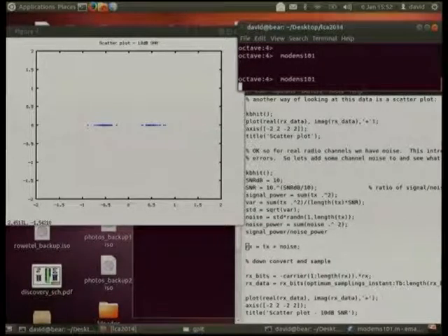Now this is a signal to noise ratio of 10 dB, which is roundabout the limits of analog communication if you're transmitting single sideband or voice. But you can still see, for digital, the 2 points in the scatter diagram are quite a long way away from this zero line down the centre. Now if enough noise was added to this side to move one of these points over to this side, you'd get a bit error. Likewise, if enough noise was added to a point that should be here to make it move over here, you'd get a bit error.